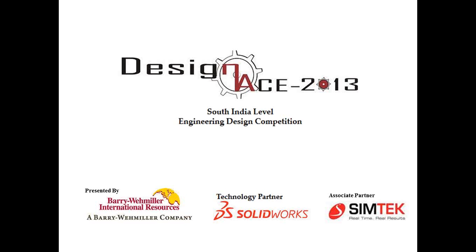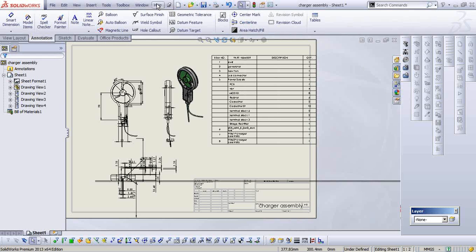This will be taken to the battery through a PCB board. It will monitor the incoming volt produced by the dynamo and helps to store it in a battery. The battery is then connected to a USB port, so the mobile phone or any accessories can be charged through USB. You may also add any design calculations to this document.